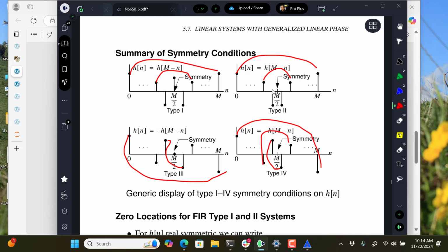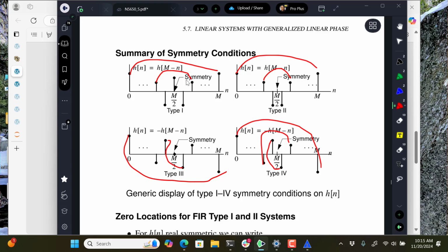If you're an FPGA person, you might say, no, I want an even number of coefficients, and I want it to be a power of 2, let's say. So then they might favor a type 2, but it might depend upon what the delay properties of the filter are. It's still going to be a constant group delay filter, but from a delay standpoint, I like the type 1 better.